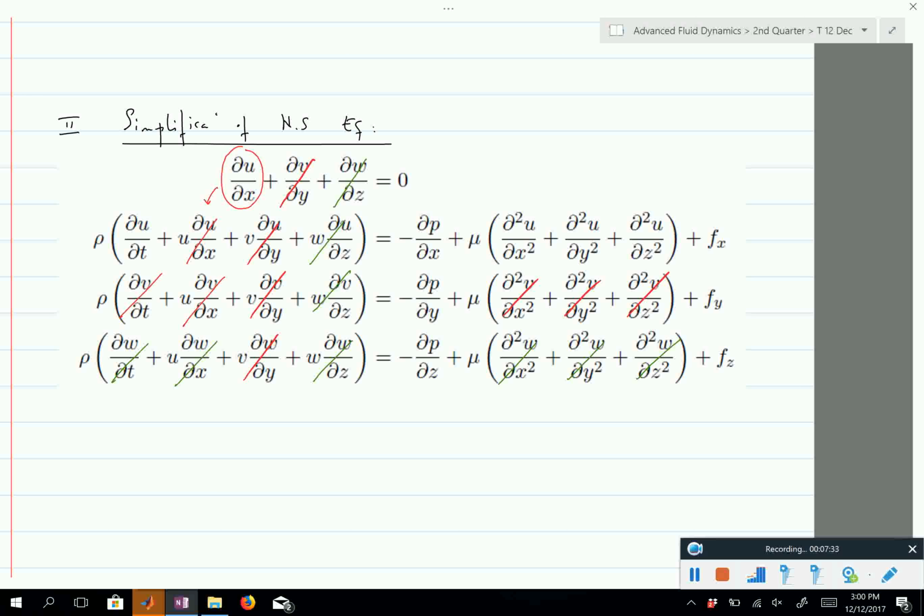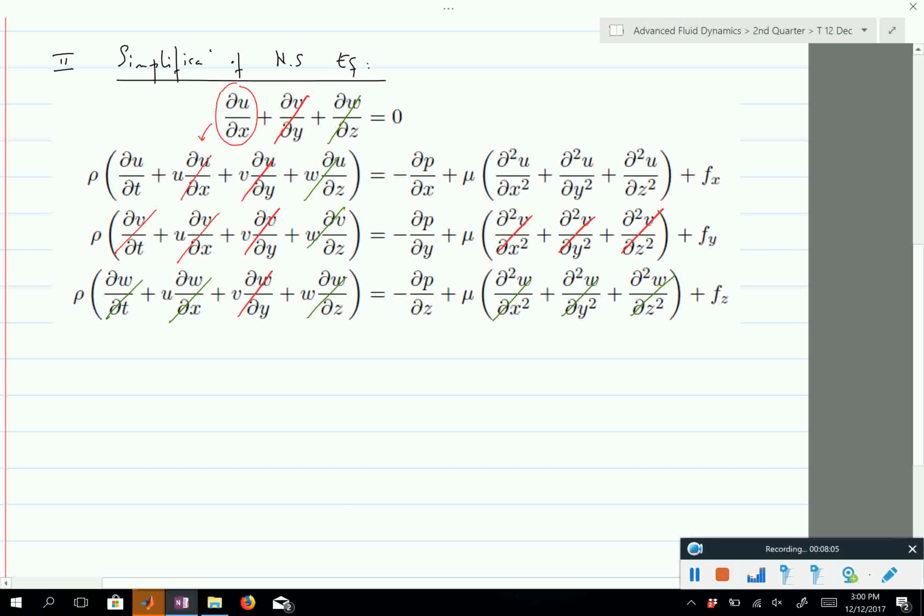Usually, up to Reynolds number on the order of 10, 100, 1,000, you have laminar flows, then the flow is unidirectional, right? The Reynolds number is not small, so in principle you would expect effects of inertia to be relevant or to be present, but if the flow is unidirectional, then because of the flow geometry, there is no effect of inertia, because you cannot change the direction, and because of incompressibility, you cannot change the velocity. Yeah? Okay. So, let's see what happens.